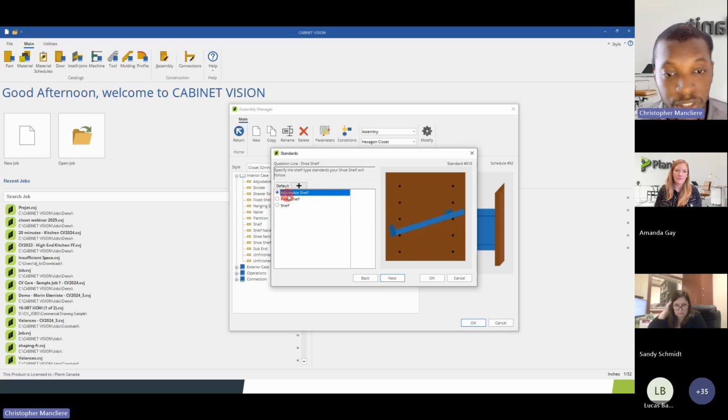and you can select if you want this shelf to be adjustable or fixed as well. So most people will use the existing adjustable shelf holes, add a shelf pin, and then also notch this shelf to make sure that it doesn't fall down. And you have options if you want this to be angled by 1 or 2 holes as well. And the last thing is you can also select if you want to notch the front, the back, or both, or if you don't want to notch it as well. Always recommended to notch it so it doesn't slip down.